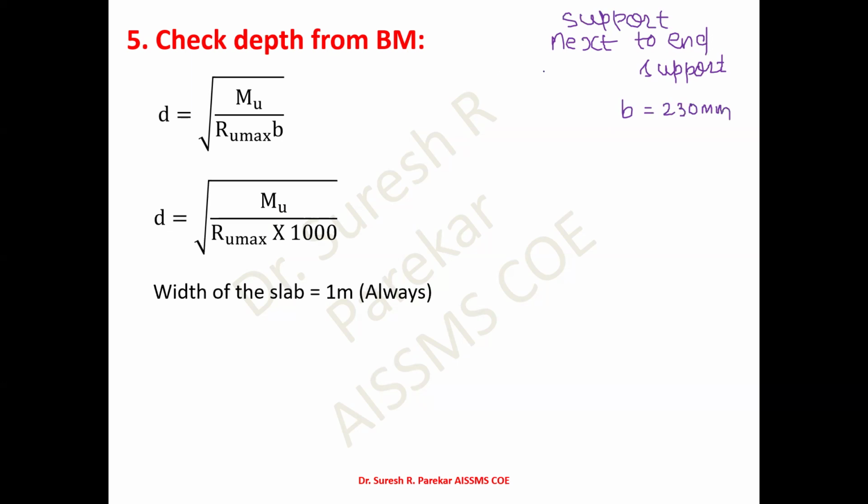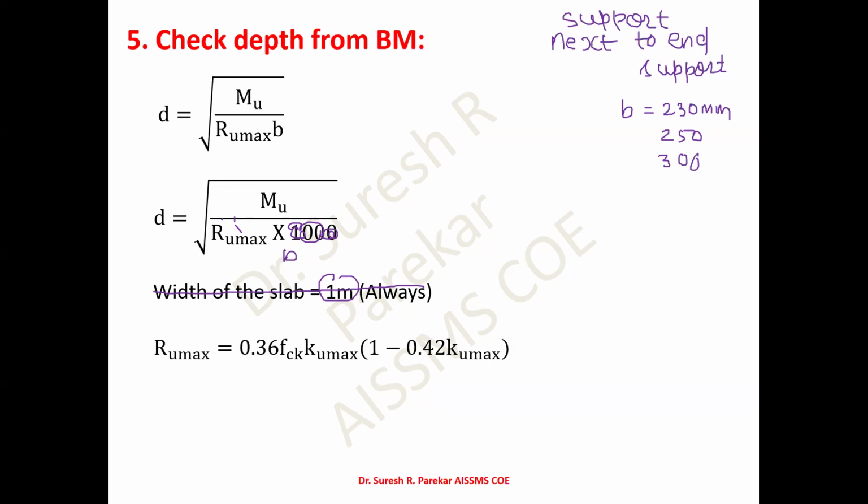While calculating the values of slab load, you have to take B as 1 meter in the slab, not in the beam. So this is for the slab, and for the beam we have the value 230, 250 or 300 mm. That you have to keep in mind. So in beams we should be careful, and the value should be in this fashion. Ru max we already know, we have this formula that may be asked.